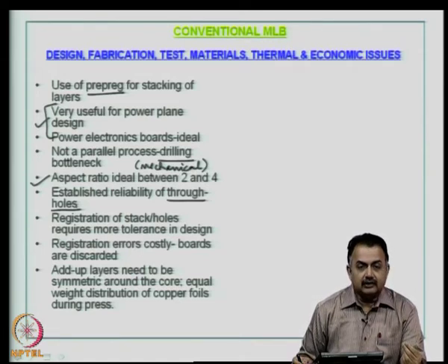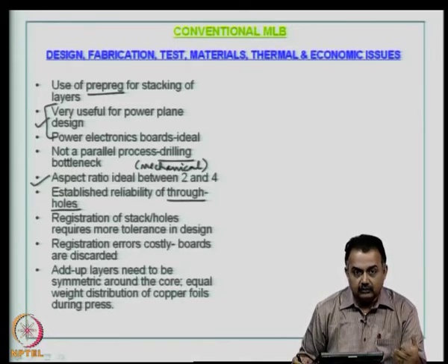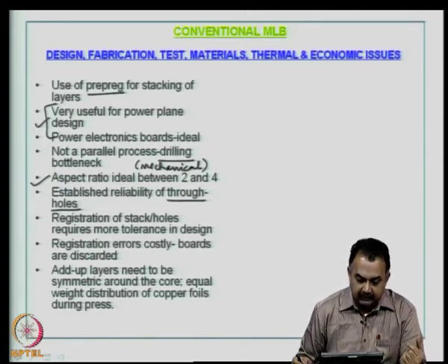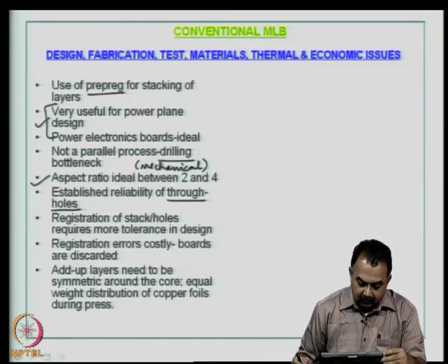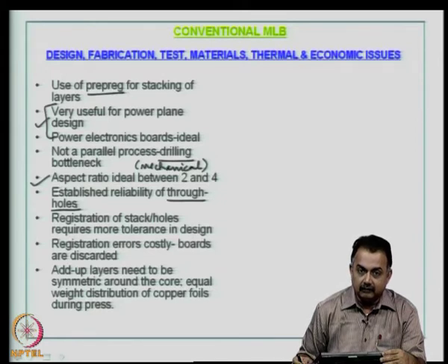The registration of stacked layers and holes requires more tolerance in design, because as you know there are guidances based on IPC, military etc. in manufacturing as well as in materials. But you have to have a good understanding about the tolerance levels, dimensions, and accordingly you have to incorporate it in your design.